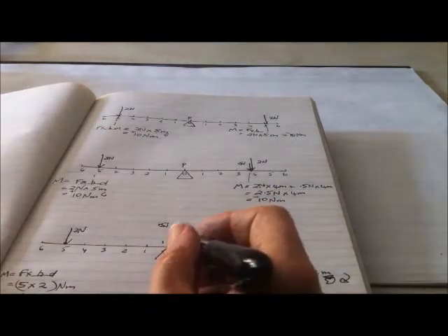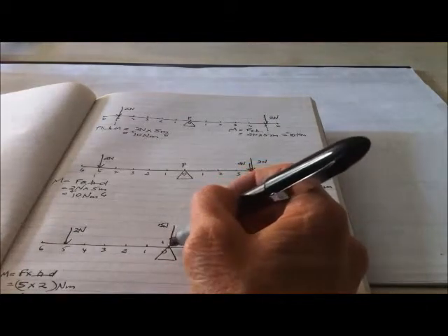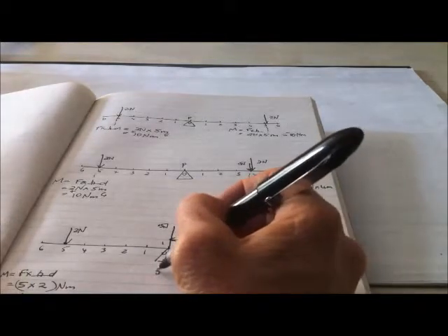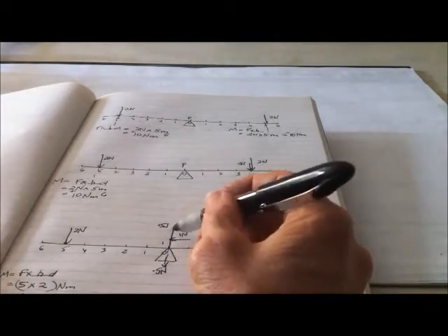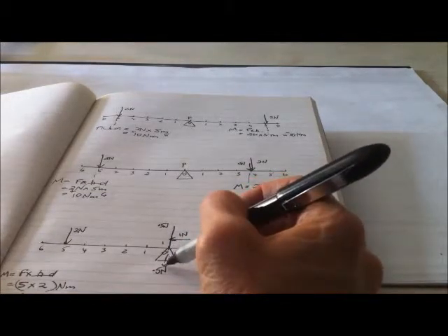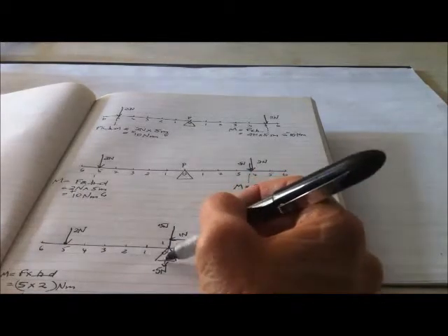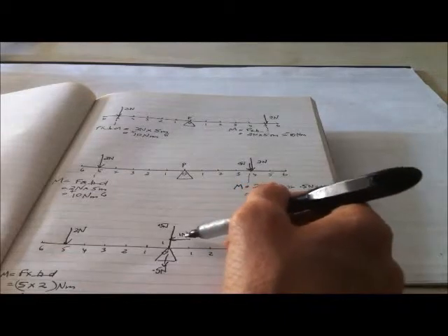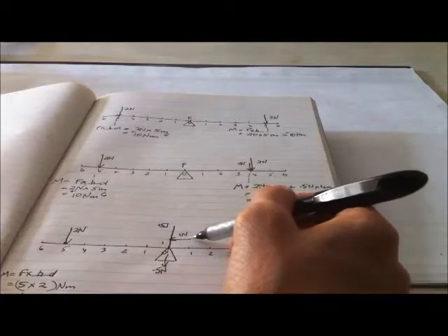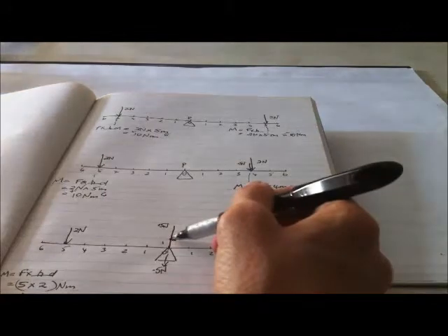But what's happening here? Well, let's consider it. The actual weight is creating a 0.5 Newton force, but it's down through the centre. So is the weight creating any moment? No, because there is no perpendicular distance from the weight of the bar. However, the force being applied to the bar is at 1 metre away, and it's perpendicular to the moment arm. So we know that it will apply a moment.